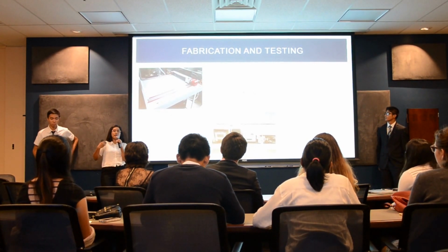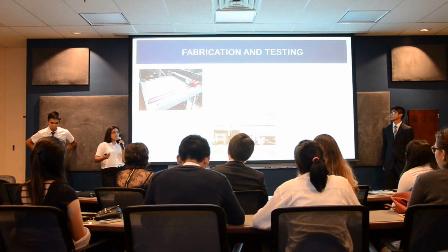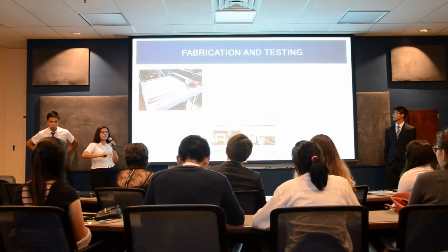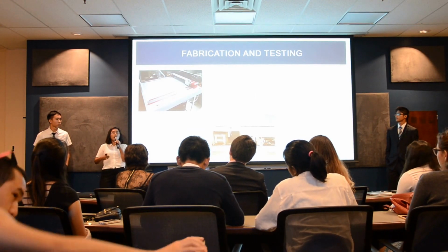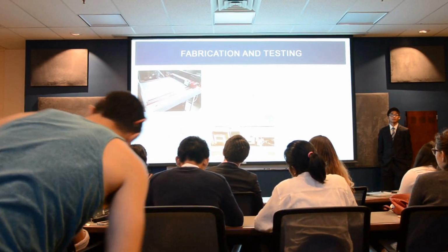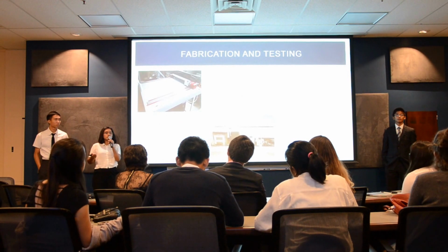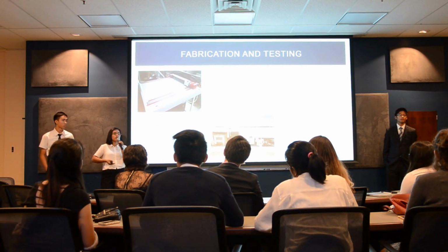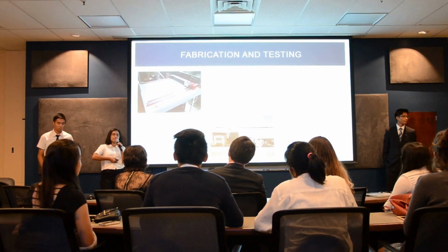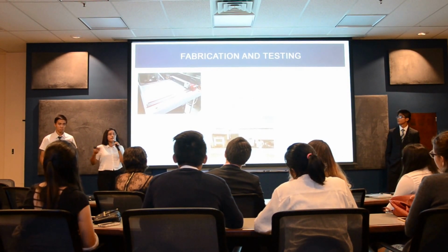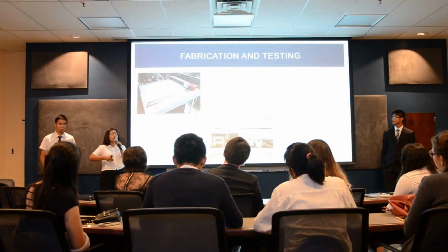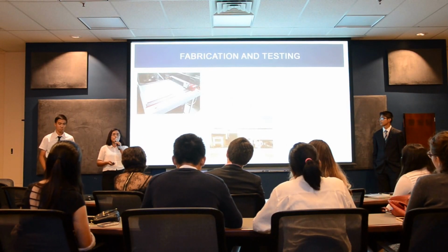What this means is that we get the material, which was a substrate and copper on both sides of the substrate, and using chemicals, we get the outline of the antenna onto this material, and then we dip it in iron chloride, which then gets rid of the excess copper. And so on one side, we're left with the design of the antenna with these features like the director and the driver and the feed. And on the other side, we have the copper ground plane.